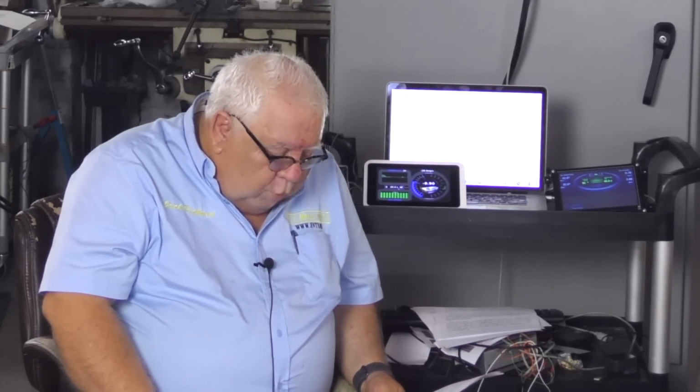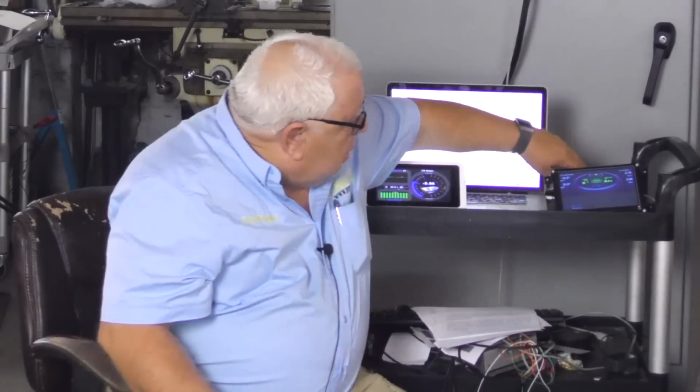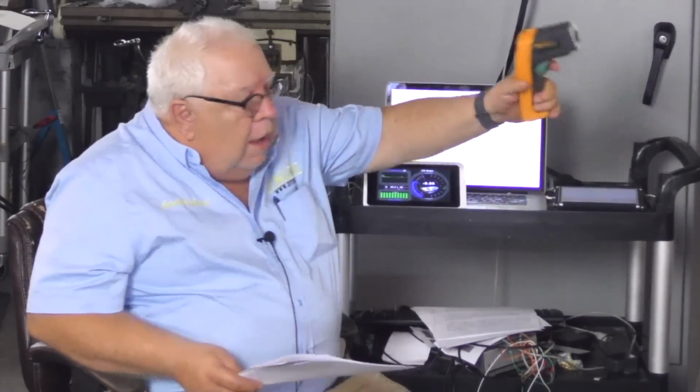But I did notice we were up over 50 C on modules 17 and 20, which are the top batteries. The ones closest to the inverter. I opened the door and hit the terminals and packs with my handy Fluke Model 516 infrared thermometer. This isn't a DeWalt or something cheapo.